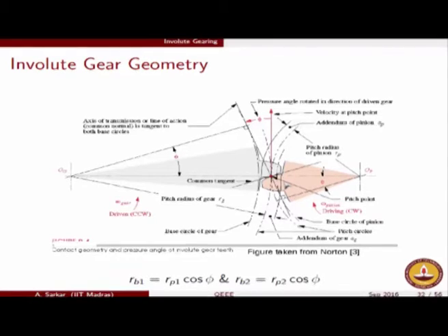So this transverse load onto the shaft will cause shaft deflection. What will happen if the shaft deflects? If the shaft deflects or sags by a huge amount, then the gear pair will no longer be in contact. So the gearing action will be lost. So therefore this is actually a menace.